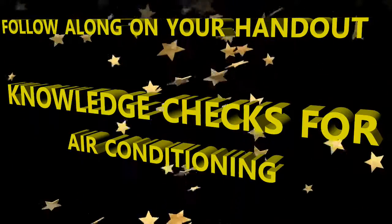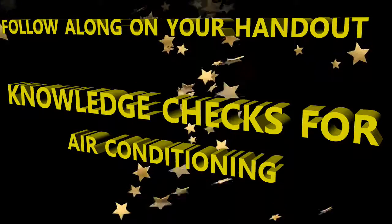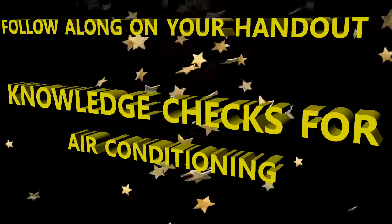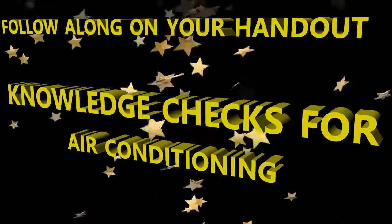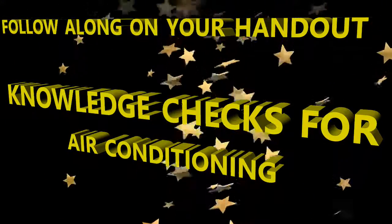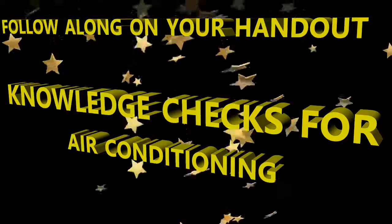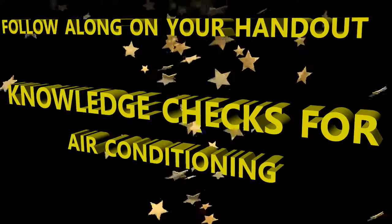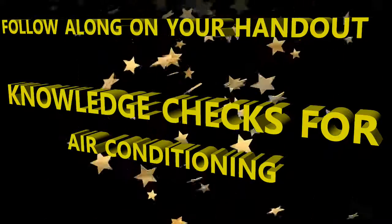Okay, where are the isolation valves located? The forward isolation valve is located under panel 151 EW, and aft isolation valve under 162 DW. Or second choice, forward isolation valve is located under panel 131 VW, and aft isolation valve under panel 162 VW. Okay, it's the former. You're not going to find the isolation valve under panel 131 anything. It's actually 151 or 162.